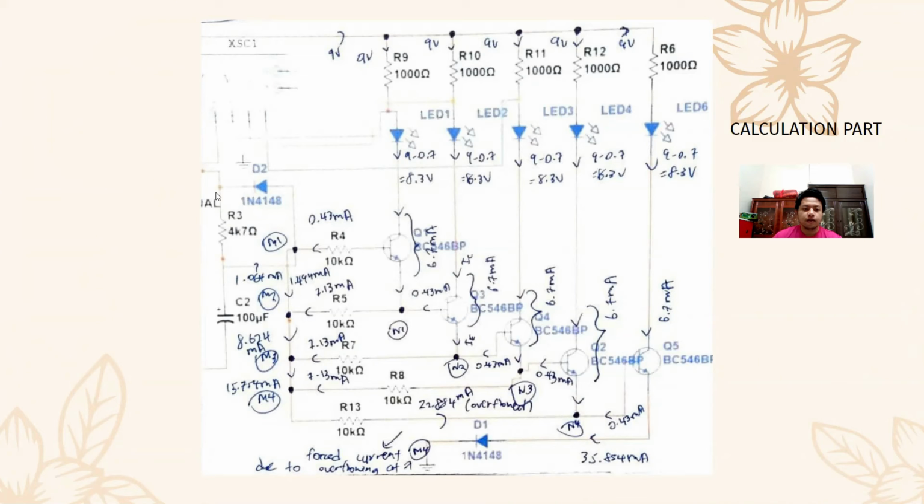From here, the power source will pass in two directions: from the top, and also from the out pin of the 555 timer, which will flow through R3 and will flow here and not here. At the end, all of the currents will collapse here and flow toward the ground.